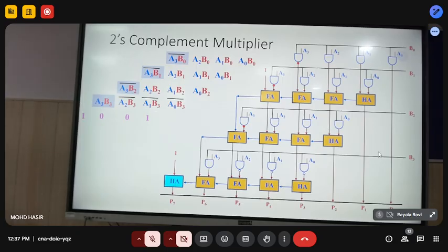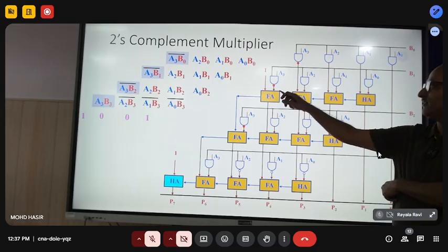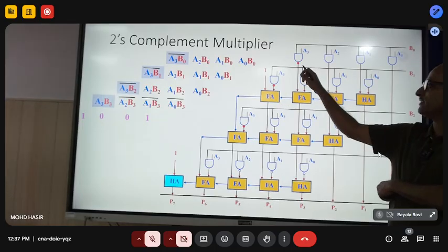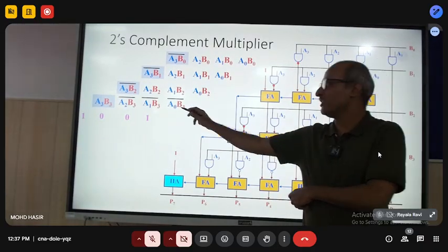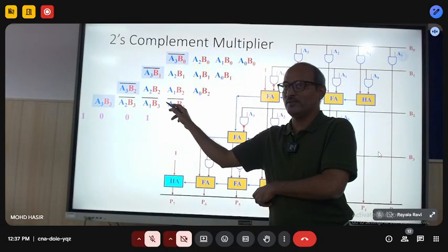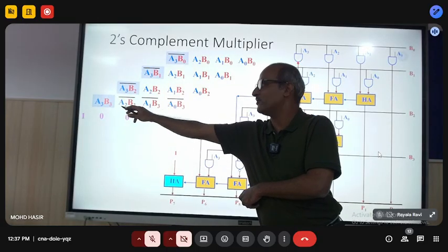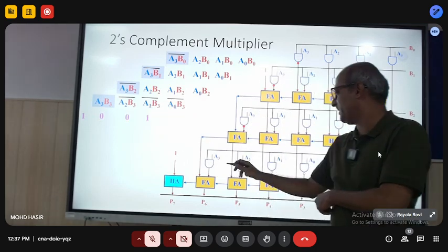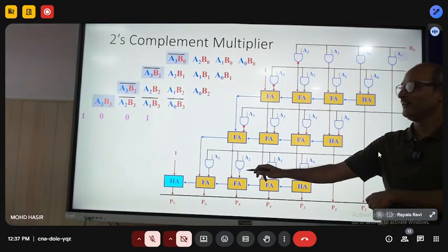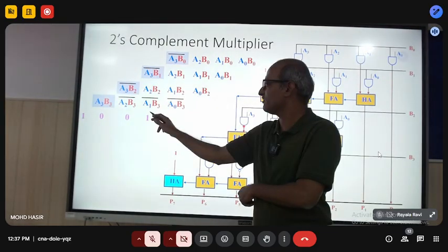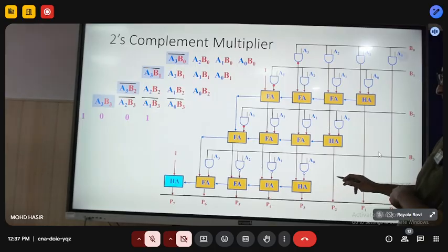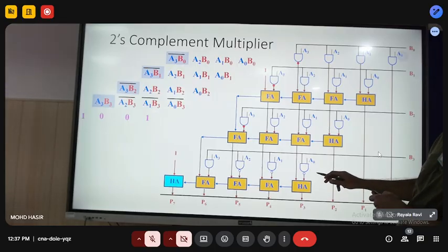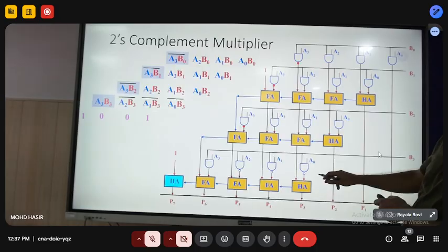Okay. And now, if you look at the structure, this is the resultant 2's complement here. MSB position complemented, others are AND gate. This one is NAND gate. Okay, so realizing this term. Okay, this was 2's complement adder. Okay, so complement of complement, this should be true. So here it will be AND gate, other places it will be NAND gate.